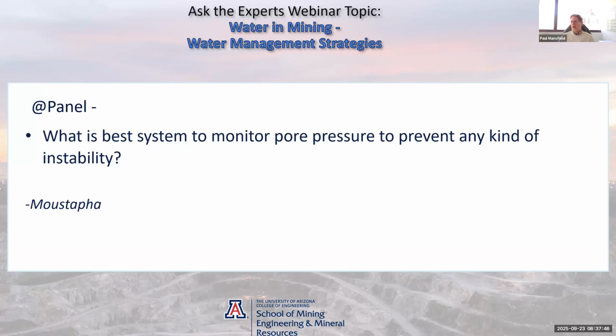Yeah, as you say, Jeremy, all this goes hand in hand with geotechnical monitoring. I mean, it's not just the pore pressure component. You have to have instrumented for slope stability, radar monitoring or prisms to identify those areas of instability.